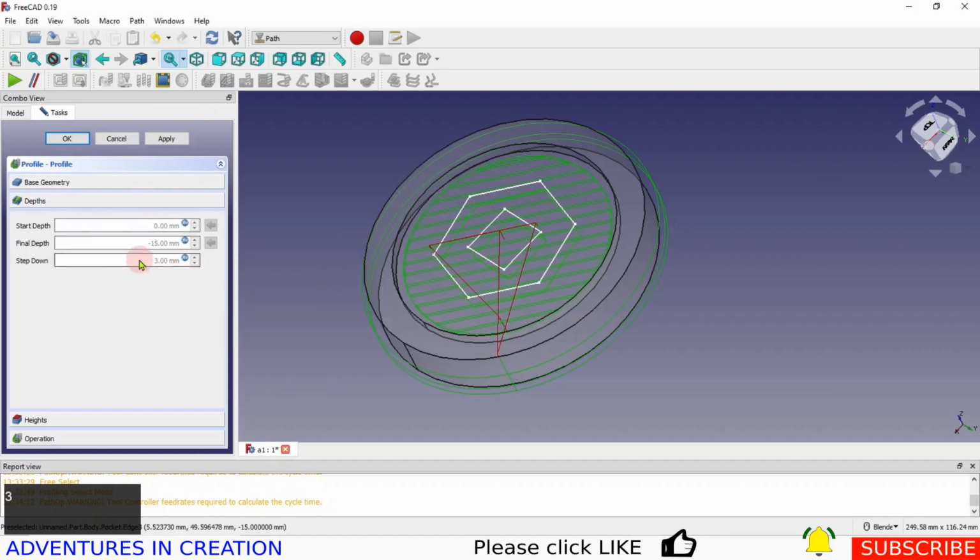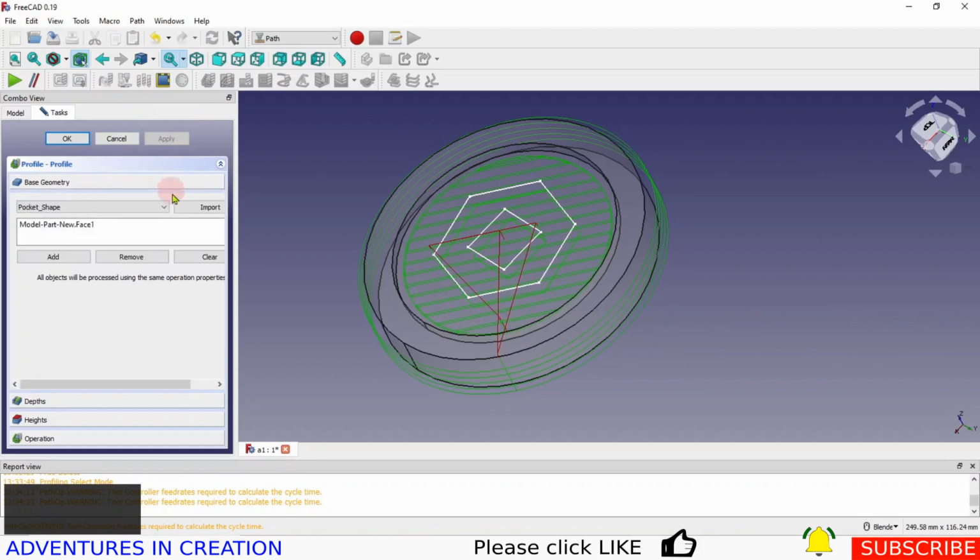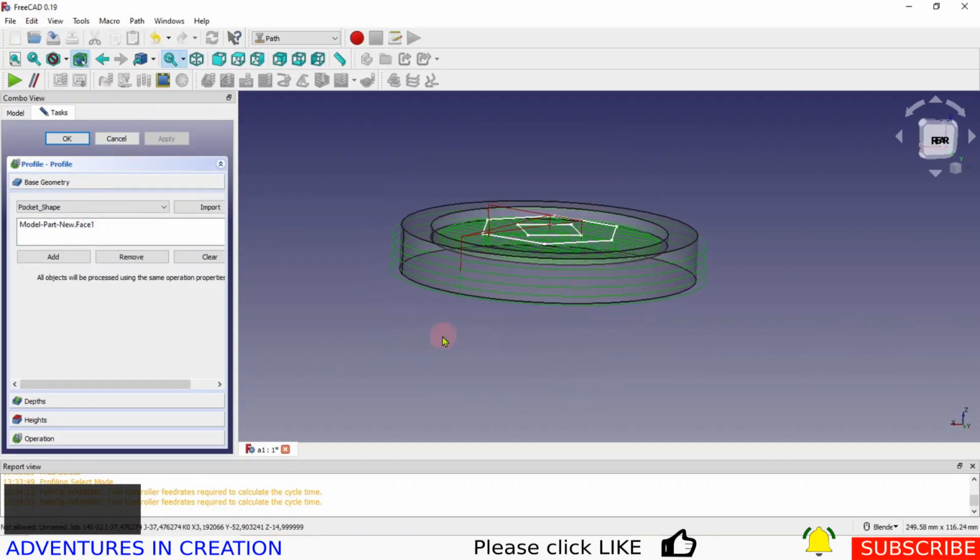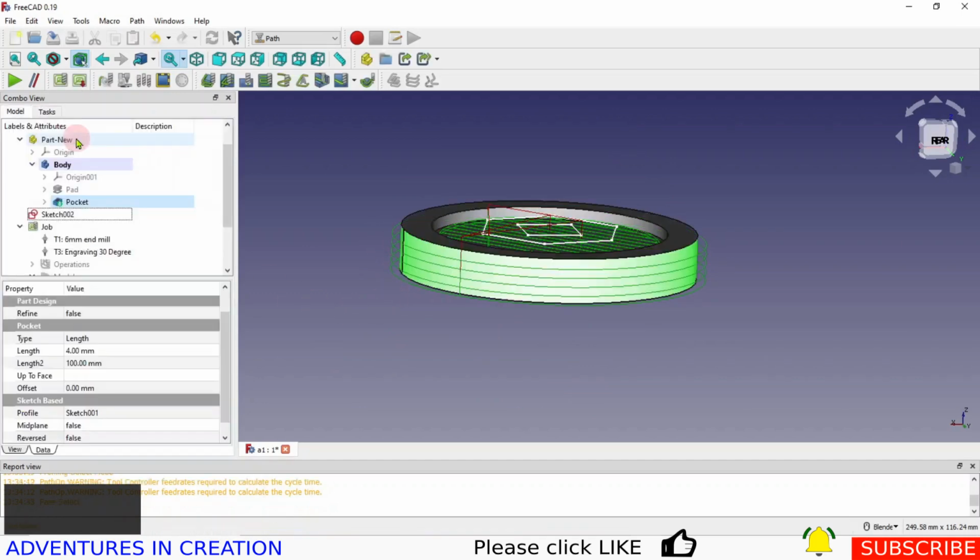So just be aware that sometimes if you change the tool, it defaults to the tool diameter, which was selected a 3. I changed it to a 6, but it didn't update this step down until I hit the apply. So now I've got it set at 3. And then our base geometry is that face. It's already selected that, and you can already see here are our cuts as we go down the side. So that all looks good.